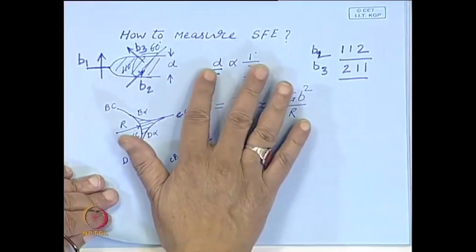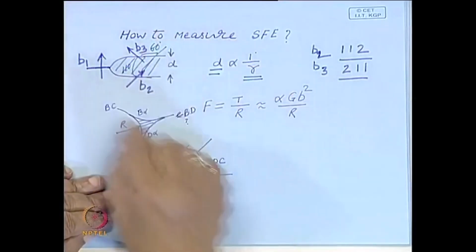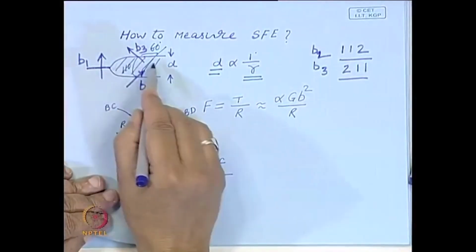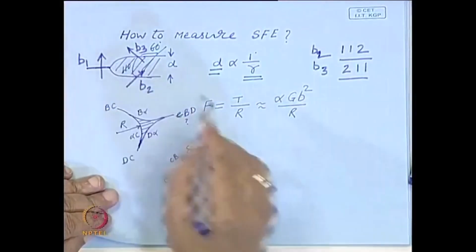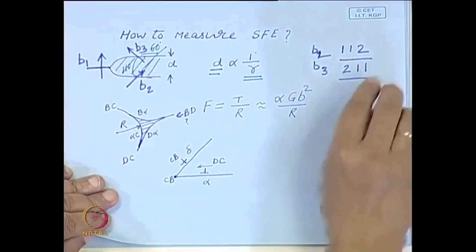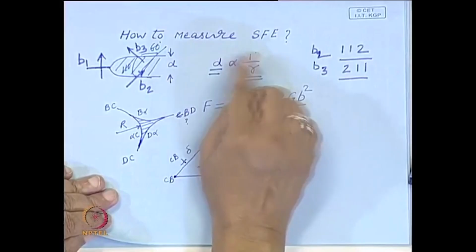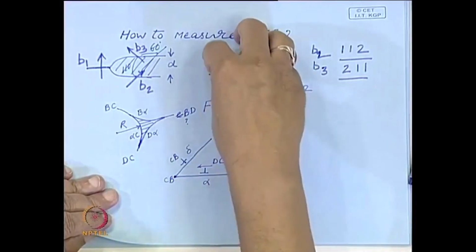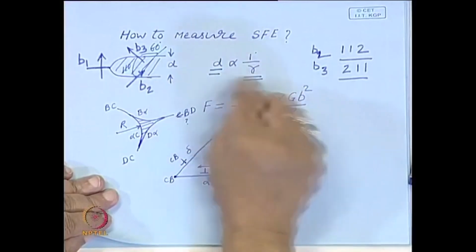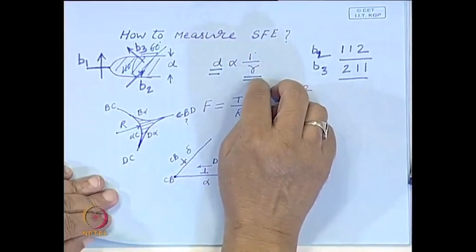Under TEM you can see these two partials separated by a fault, and the faulted region also gives stacking fault fringes. So, this is one way of finding out the stacking fault energy, but it will be applicable only in cases where the stacking fault energy is very low.